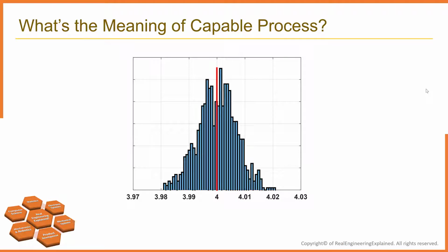Now let's go back to process capability. Process capability is the ability of a process to meet the design specification for the service or product you are providing as a supplier. It tells us how good the individual part is. It depends on 2 values. First is the nominal value, which is a target for the design specification, and the second one is the tolerance or specification limit, which is the allowance above or below the nominal value.